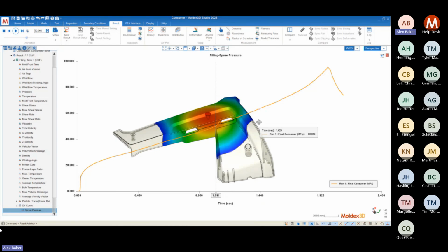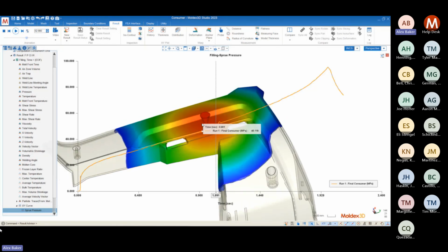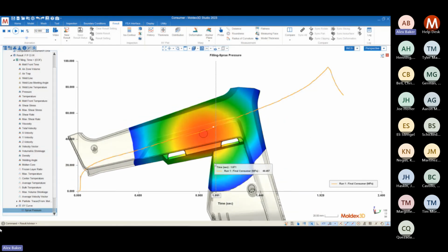And what ends up happening is that as the flow develops, it has a choice in going one of three directions. It can either go towards the top right, bottom right, and the left side. Once the material has completed filling the top right corner of our part, the momentum of the material that was going in that direction has to shift to either going towards the bottom right or towards the left side of our part.